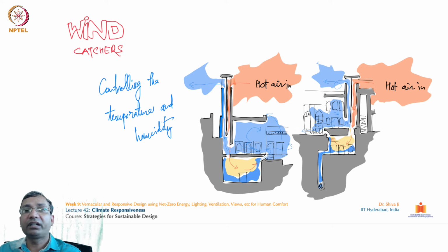The main function of these wind towers is to receive the wind and bring it down into the lower quarters of the building. While going below the building, this air gets in touch with the colder wall surfaces, and even sometimes the water element which is flowing below the building, and then it rises, cooling the temperature in the other quarters of the building. So this is one of the very interesting techniques which has been popular in several vernacular architectural systems from across the world.